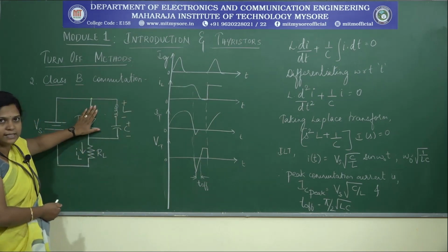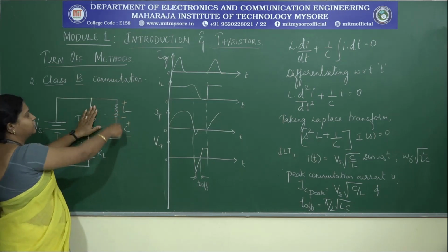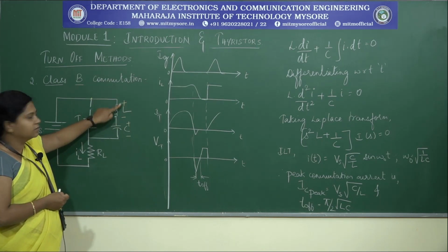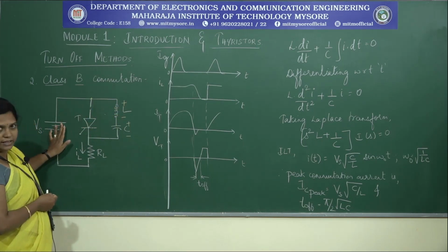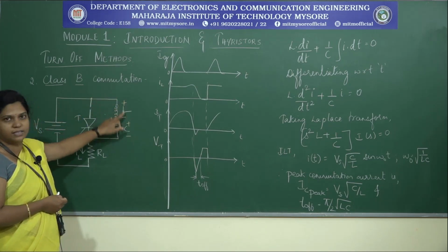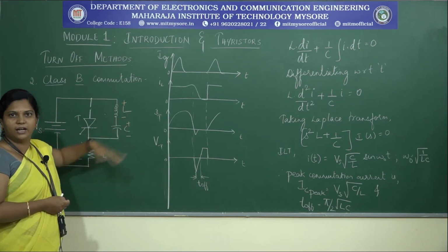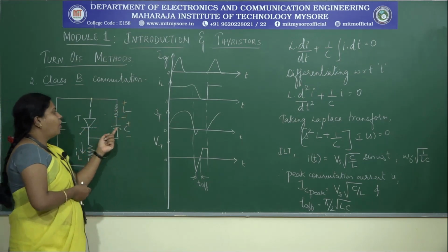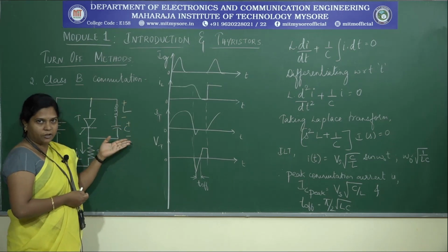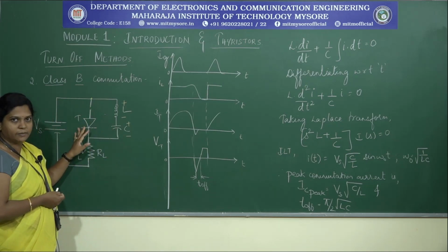So when the thyristor is in its off state, the current flow starts through this path. Since it is a positive polarity that we are applying here, the energy storing will also take the same signs. Plus and minus, in the inductor energy is being stored, and on the parallel plates of the capacitor the charges are also being accumulated, before we turn on the thyristor.